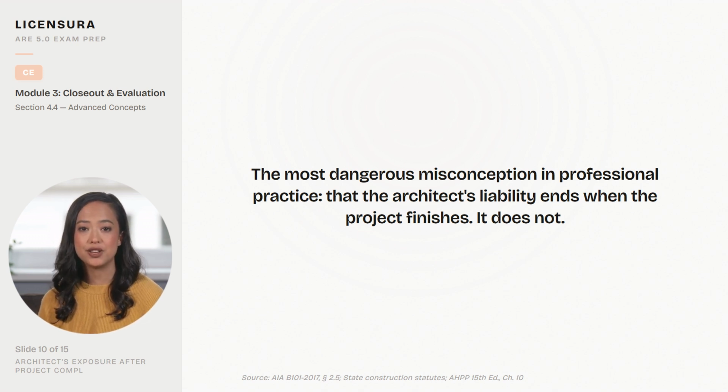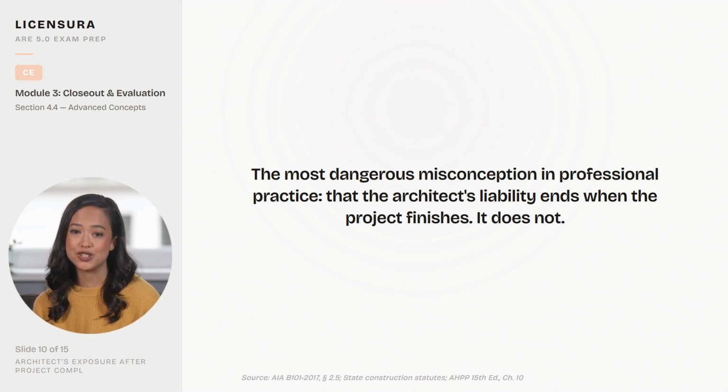The architect's post-completion exposure is bounded by 2 statutes: the Statute of Limitations, how long after discovering a defect can you sue, and the Statute of Repose, absolute cutoff regardless of discovery. Both vary by state. Both can extend the architect's liability well beyond what most practitioners assume.